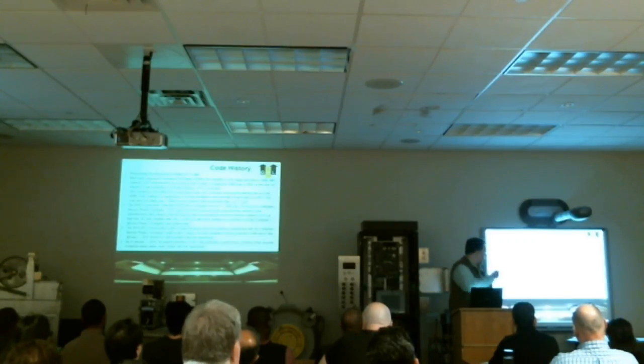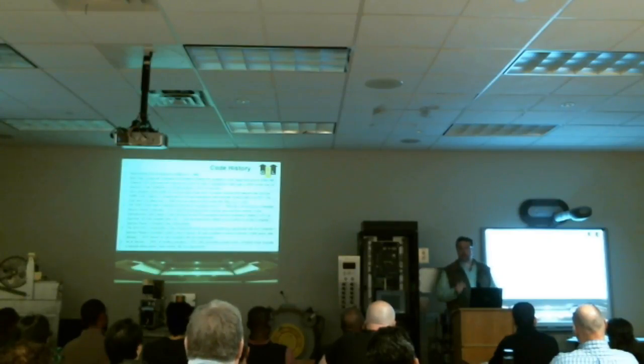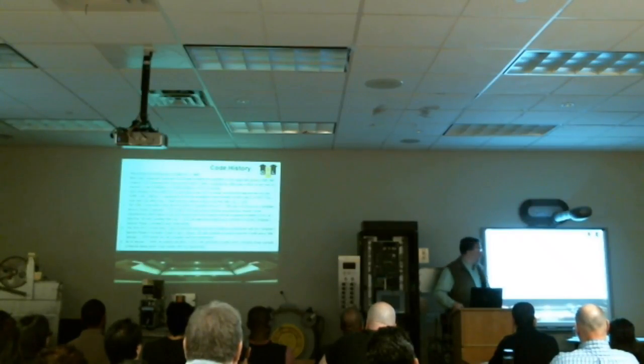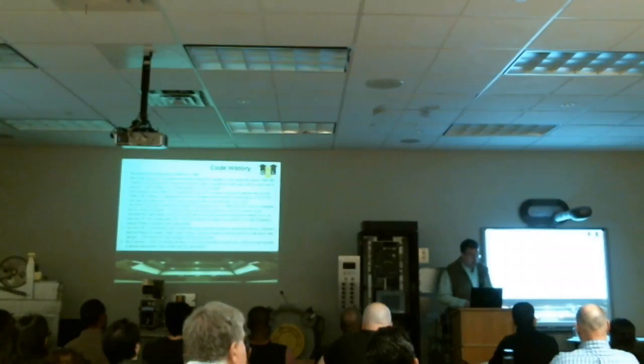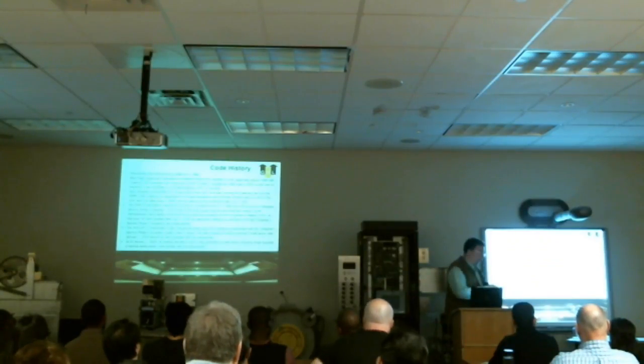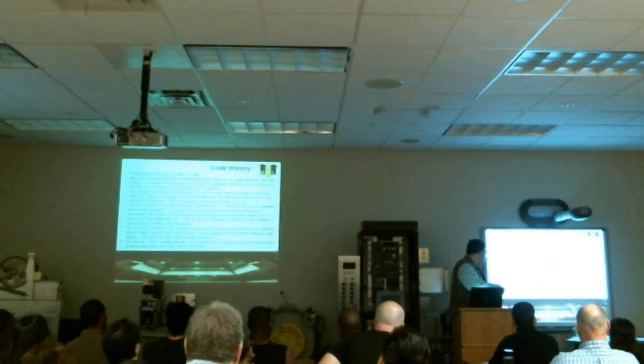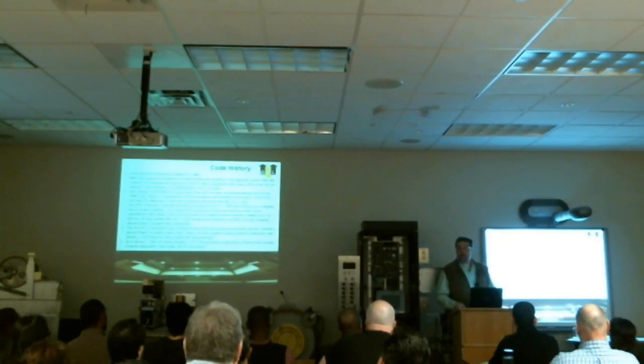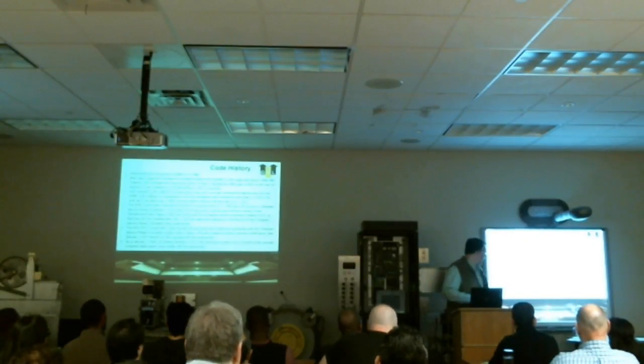And that's when it said, okay, you have to have some means of door lock monitoring on all control systems installed, new, or even going back 30 years. Every single elevator in New York City has to have some sort of door lock monitoring capability. And all of these elevators have to comply by 2020. That's the deadline. All the elevators in New York City have to have door lock monitoring by January 1st of 2020.